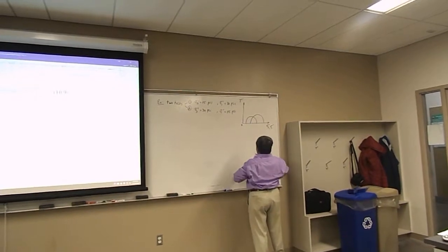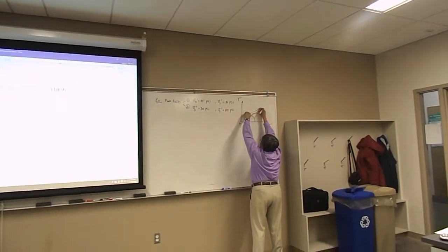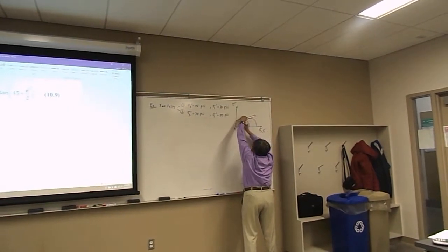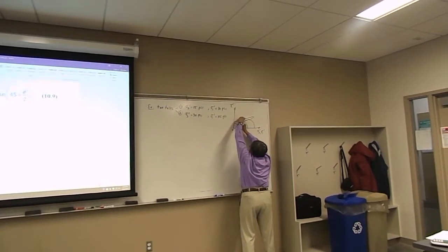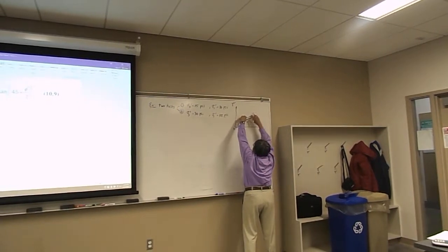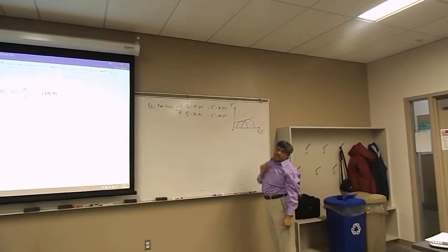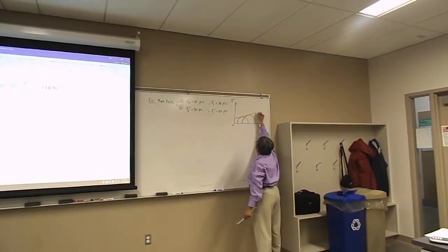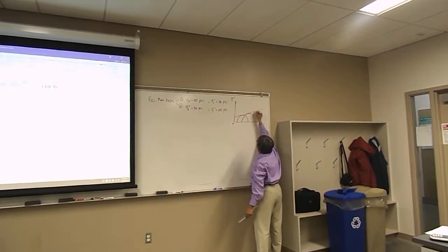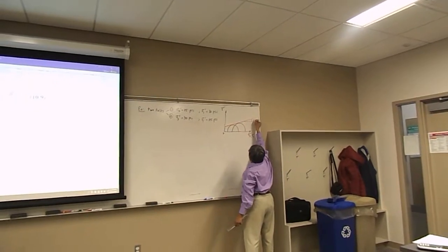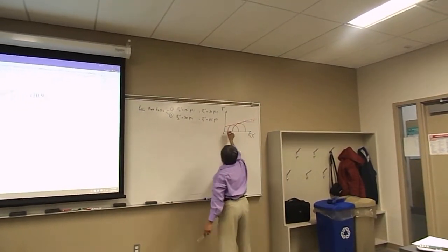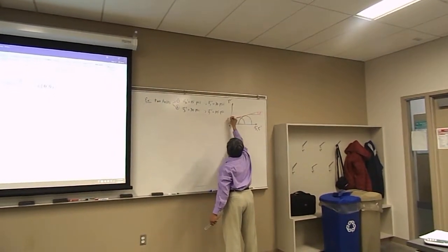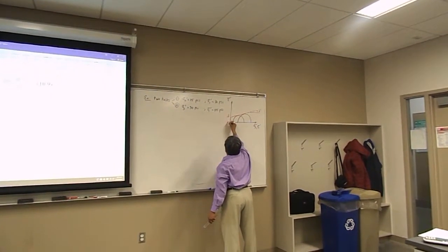Let me draw the Mohr Coulomb failure envelope. It just touches the two circles, so that is the failure point, and measure its slope angle as phi prime. You can also extend this and draw that, and this is C prime.